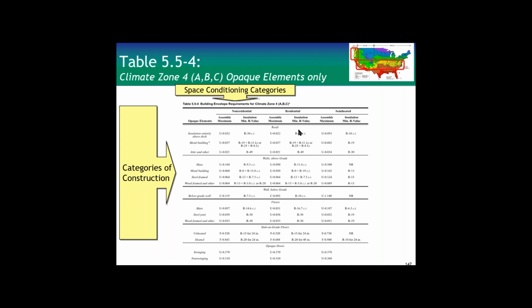So if we look at what we have, U values for all the different types of construction: wall construction, roof construction. We have R values, and if you use the R values given, even if you use brick or stucco or anything on the outside, you don't have to worry about anything else but those R values. And if you stick those straight in, then you've complied.